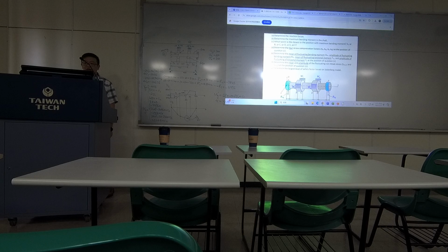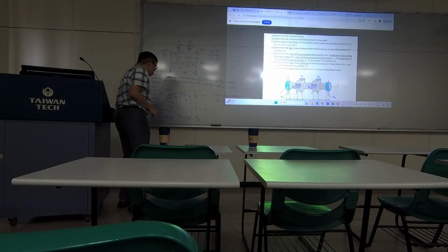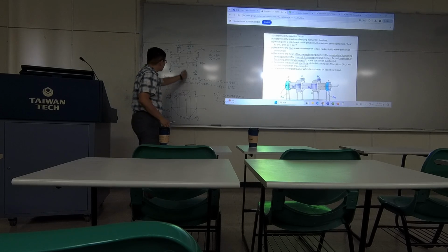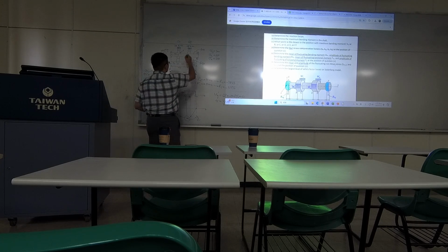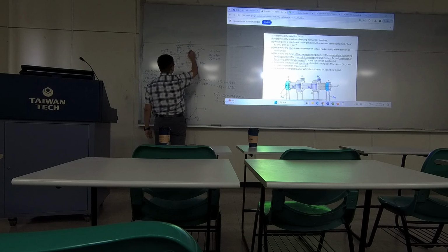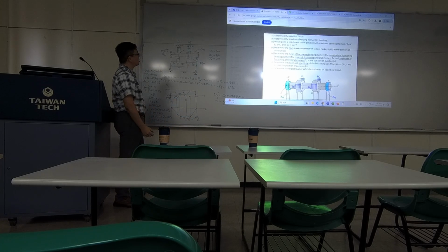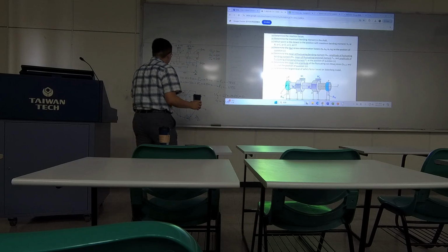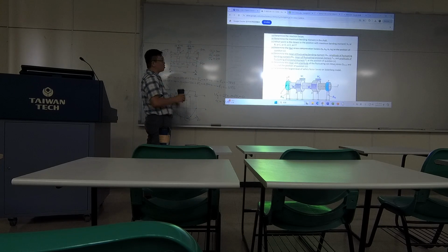Now, you need to do the fatigue model. In order to apply the fatigue model, you basically analyze right at this position. Okay. So you need to care about the stress concentration effect close to this corner.